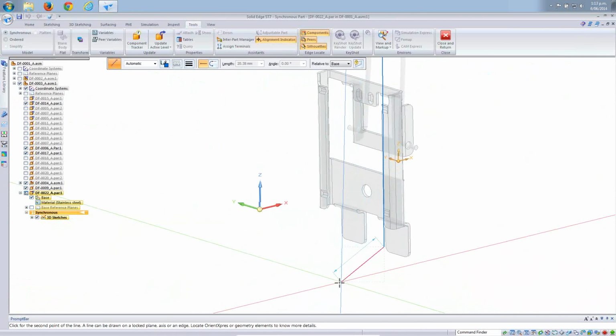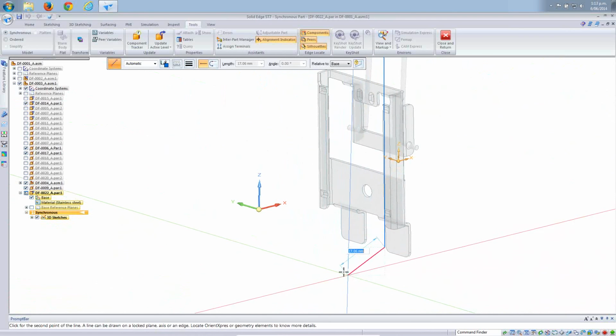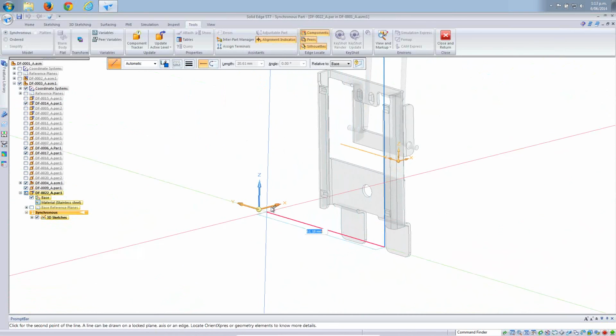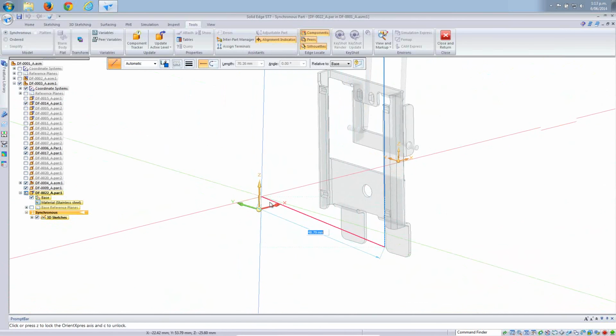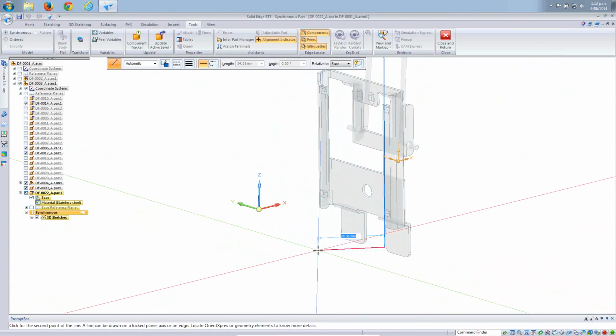Now, in the first example, when I was setting the orientation for each of the sketch lines, I was clicking on elements in this triad. You don't have to do that. There are some shortcut keys you can use. If I press Z on the keyboard, for example, it'll toggle through each of the axes from the triad.